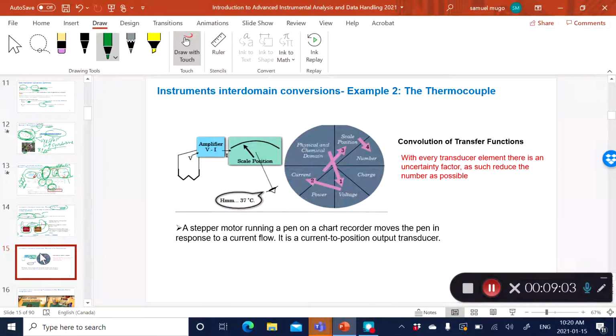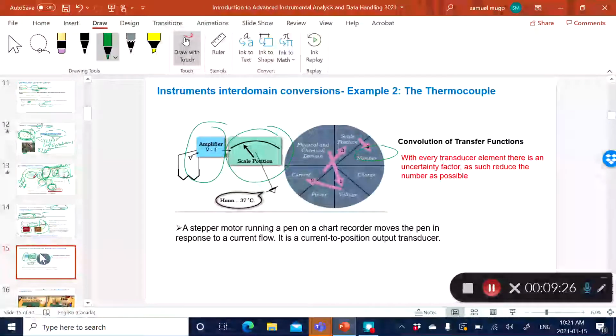And so now you've got the voltage in that case, and of course you can easily digitize it using an appropriate electronic digitizer to give you a number. And now that becomes a number which is a non-electrical quantity in this case. So you can see, the input transducer is a thermoelectric effect, the thermocouple, two dissimilar metals joined together, a very simple detector, and then you've got a digitizer at the end, converting the voltage into a digit.